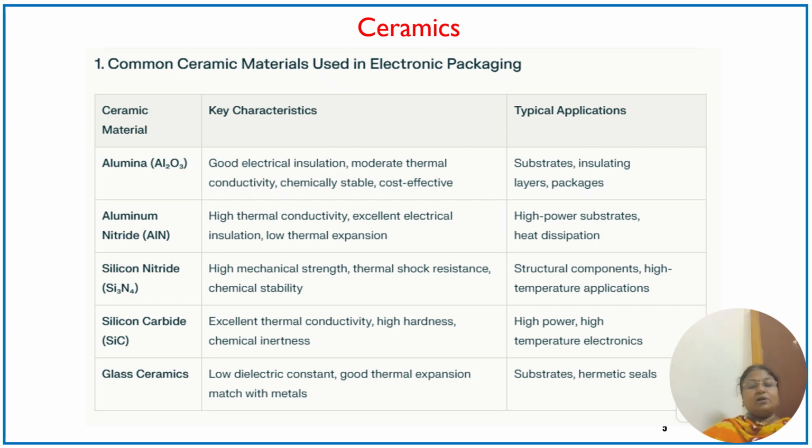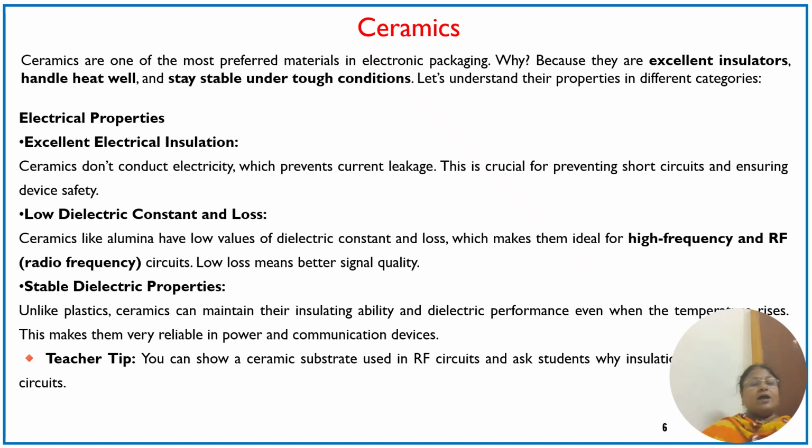And glass ceramic is a combination of glass, with a transition temperature of a glass material, superimposed with a ceramic material which possesses a low dielectric constant, and it is a substrate which is used for thermal and hermetic sealing. And the electrical properties: excellent electrical insulation, low dielectric constant, stable dielectric properties.